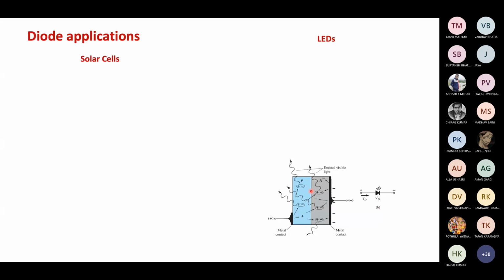Sir, because when the electric field pushes the carriers towards the junction, new electron-hole pairs will be formed, so they can recombine there. Exactly. So that is the point. Yeah, you're right that we need the diffusion component of the current, because that component essentially pumps more electrons and holes into the junction, because as soon as we apply a positive voltage, it reduces this barrier.